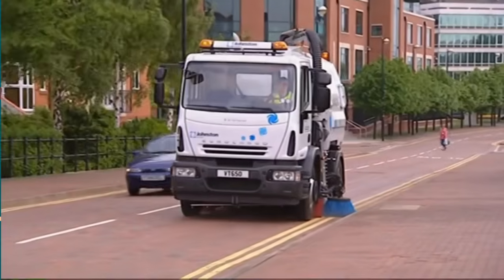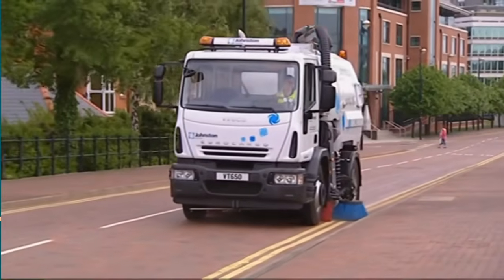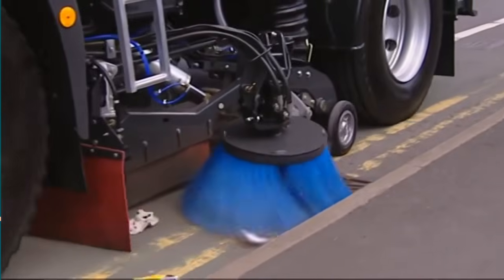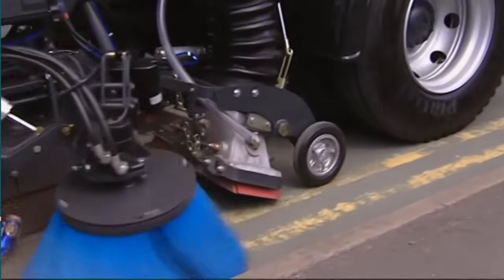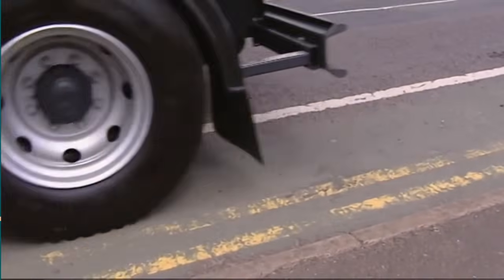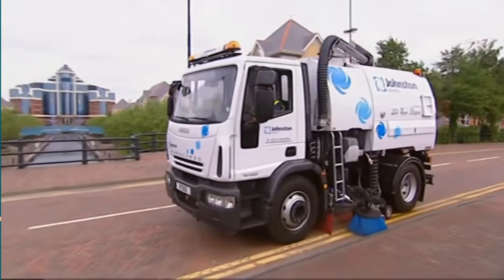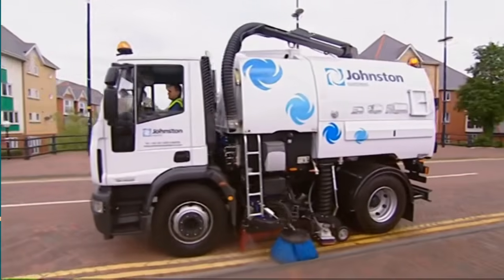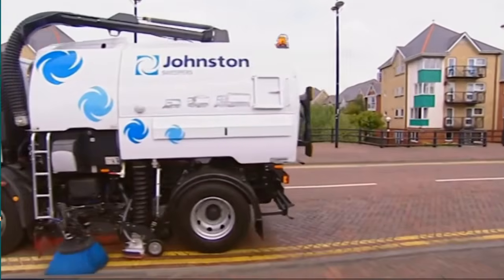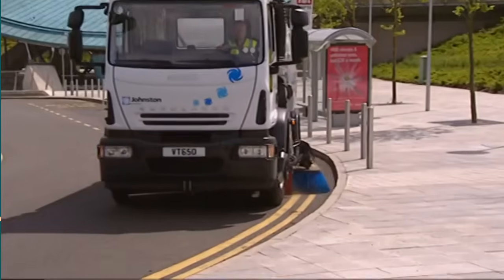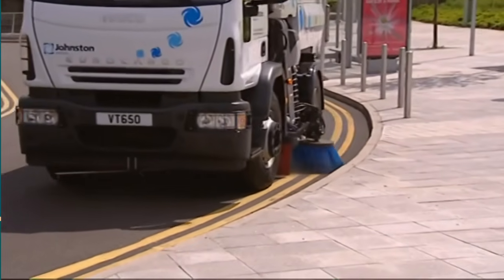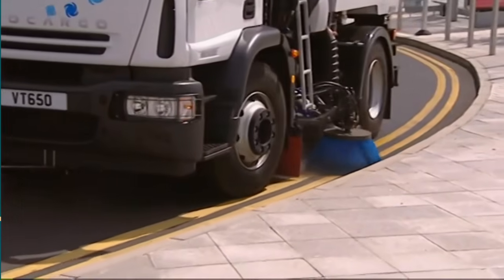The work of laying shall not be taken up during rainy or foggy weather, and if the surface of the base is damp or wet, or during a dust storm, or when the atmospheric temperature in shade is less than 10 degrees. Preparation of base. The surface for laying shall be free from dust and foreign matter. It shall be swept clean by using a mechanical broom or blown off by using compressed air.